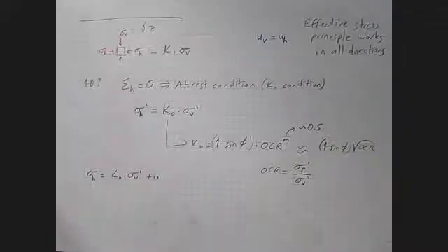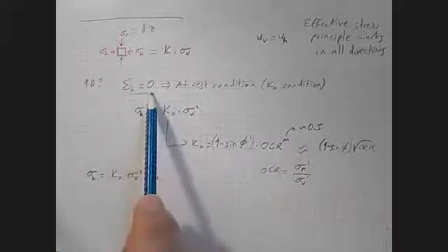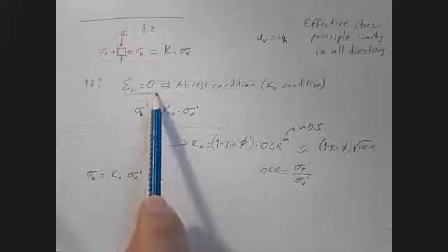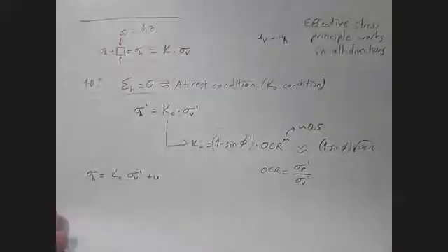Okay, so horizontal stresses are, as you see, very simple. This is it. But here we have limited this solution. This is the limitation. We have limited this solution into having horizontal strains to be zero. But what if they are not zero? What if you have some horizontal movement in the soil? Then things change.